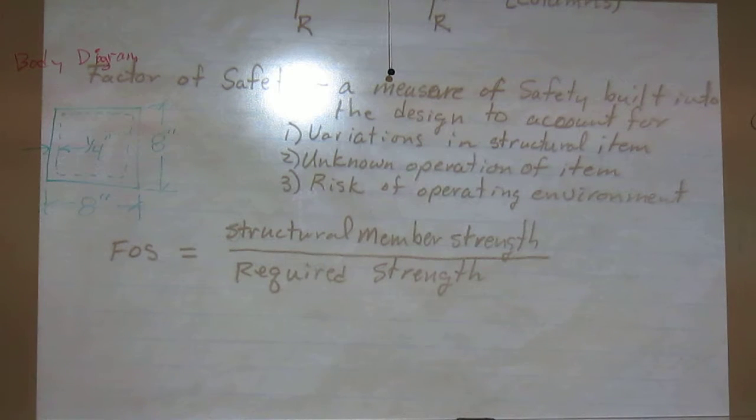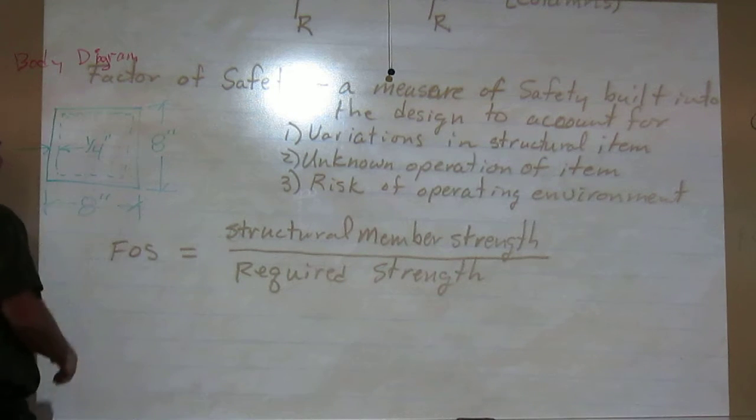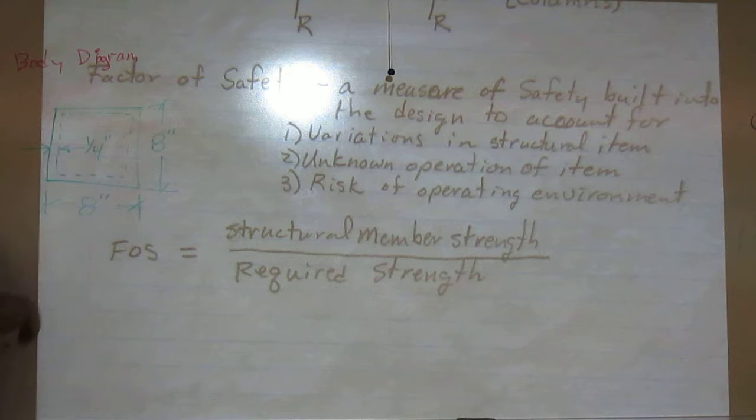Do you want us to draw the hidden line? On the section view, this would be the top view, and we're not going to be able to see it, so that's going to be the thickness. When you're drawing the side view, it'll look something like this, and there'll be a little hidden line that's a quarter inch in right here.